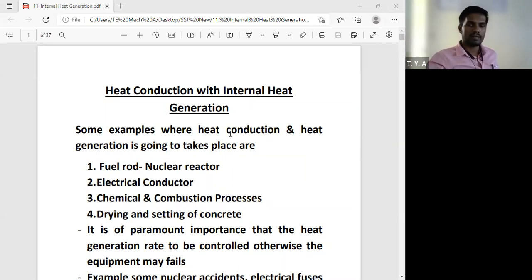So, what are the different applications for this? Steel pipe, steam pipe and electric cable. So, what is the condition for the electric cable? Insulation radius R2 is less than critical radius RC. And what about the steam pipe? R2 is greater than RC. Okay, so all of you get this point, critical radius of insulation.